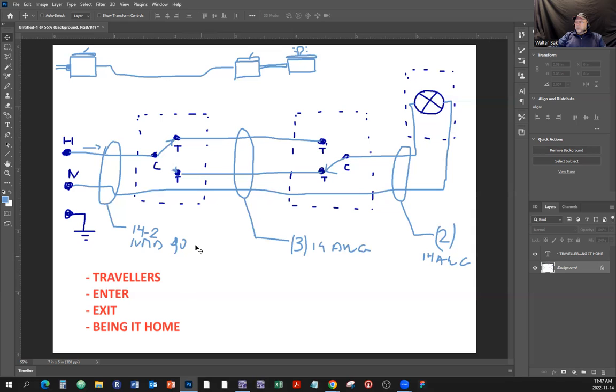Then we're going to pull the single conductors between this box and this box, leave a certain length for you to work with later, and cut them off. And we're going to get two conductors from here, same thing, leave a length, cut off, pull it to here, leave it and cut off.